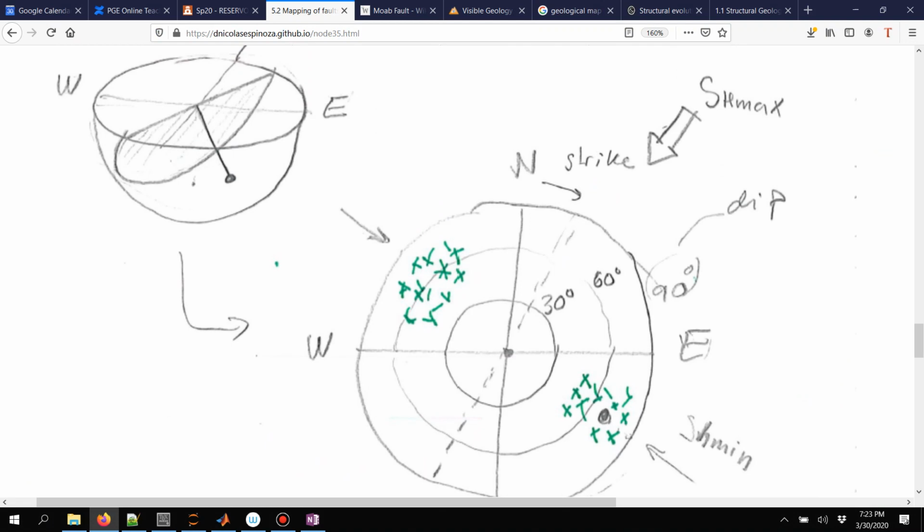If I had a horizontal plane, that would mean a dot somewhere over here, and that would be the position right there. And depending, for a given dip, like for example this one, on where this pole is moving around this stereonet, that also tells me the strike, because as I move this, the line perpendicular from the pole to the center, this perpendicular line is the line of the strike.